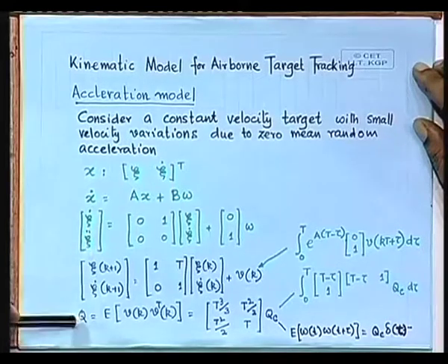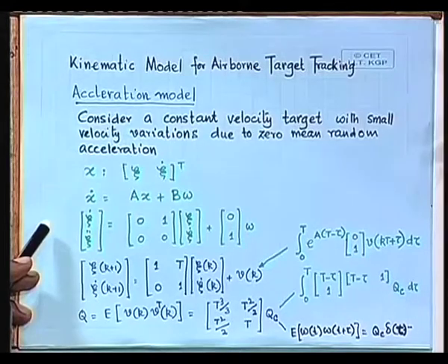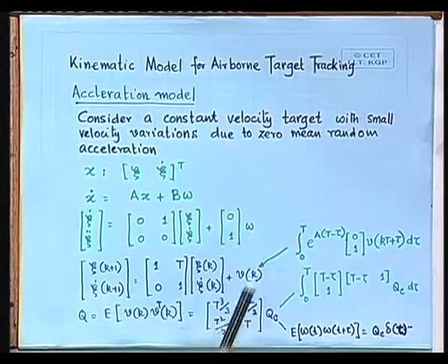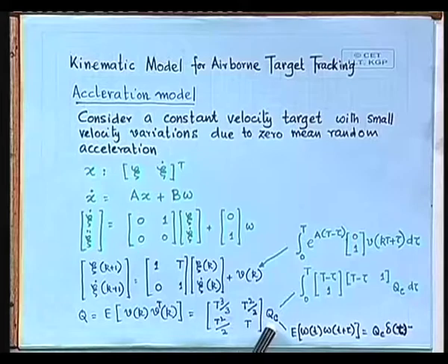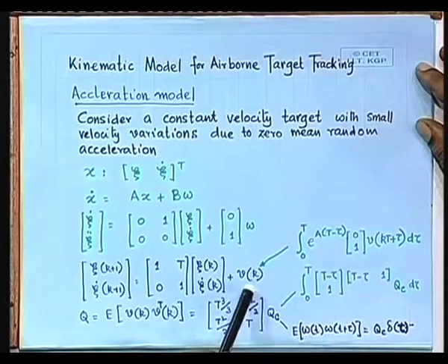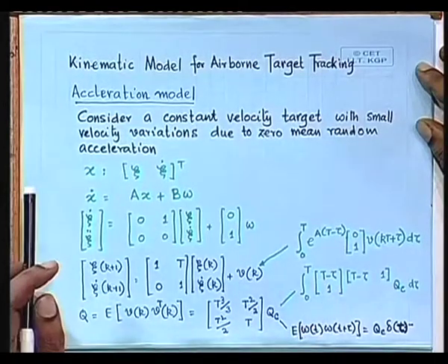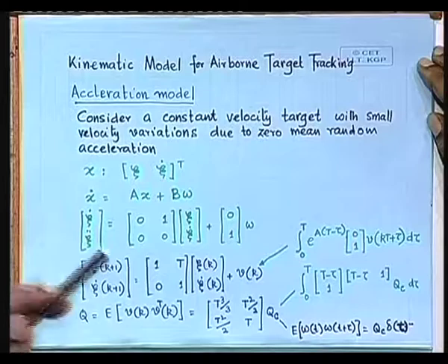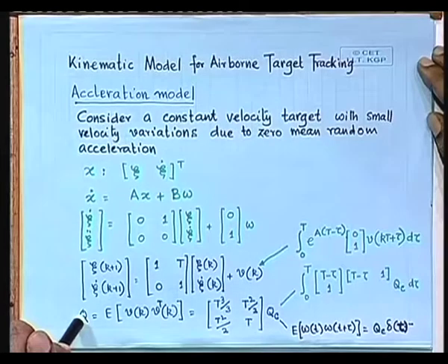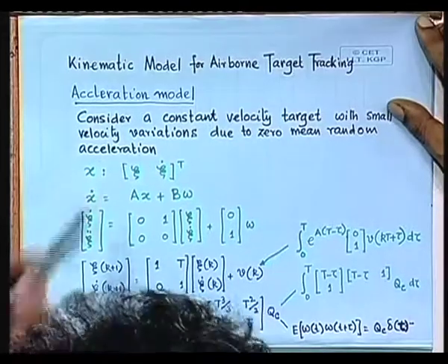Now you have to estimate what is q. You have to get the discrete time estimate of q, that is the process noise, because this process noise is not this process noise. So if you have a continuous time process noise, the discrete time process noise is related to the continuous time process noise by this matrix. We have already found this, so this will turn out to be this. That is simple. If you know the continuous time signal covariance, this will be the discrete time signal covariance, so they will be related by various functions of the sampling time, right.